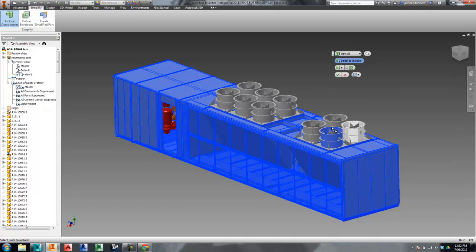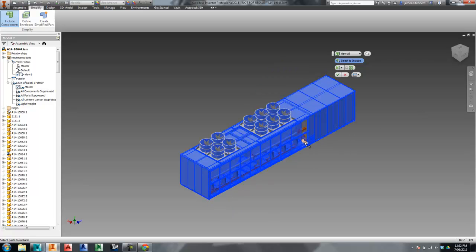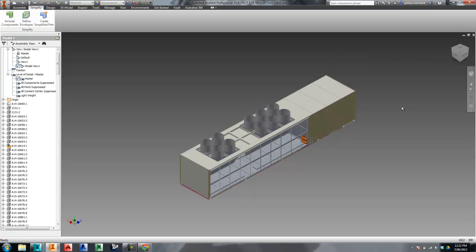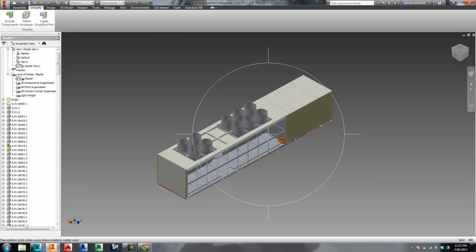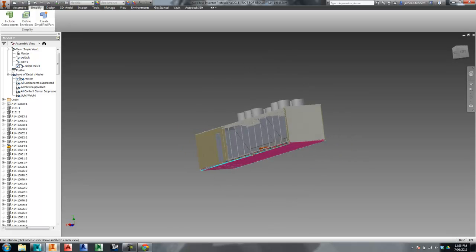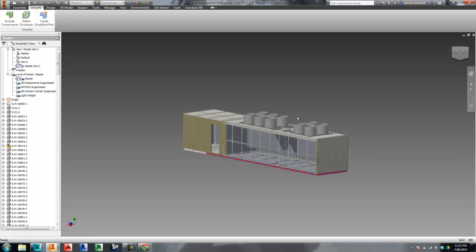So I'm just going to select each of these exhausts. And I've also got a part around the other side that I want to have a look at as well. So that's this part here and this part here. Great. Once I go OK, in that view it'll get rid of everything except for the components that I've selected, which will lighten that load massively. There it is. I'm now left with only the components that I wanted. You can see all the internals and everything have been cleaned out, reducing the size of the model, reducing the size of the view, I should say.